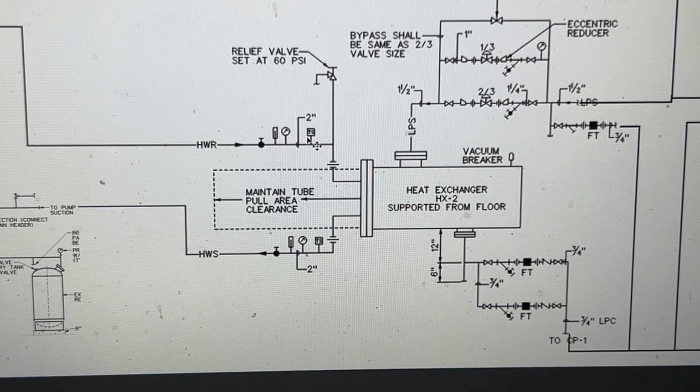There are temperature sensors on the inlet side and the outlet side to monitor what the incoming temperature is and the outgoing temperature is, and see if we have to make any adjustments there. So the 1/3, 2/3 is set up for that. In minimal load, the 1/3 valve will be utilized. If the conditions are much colder, the 2/3 larger line will be open for that.